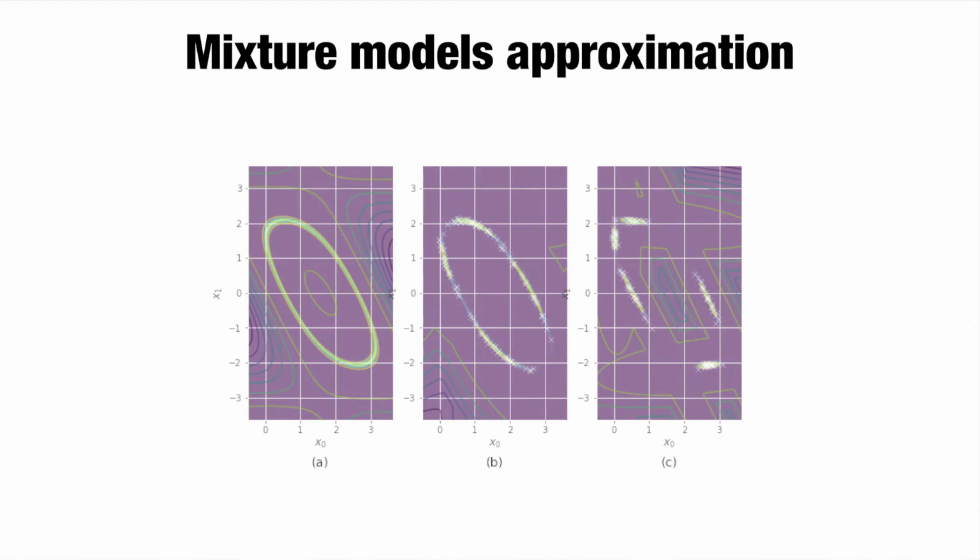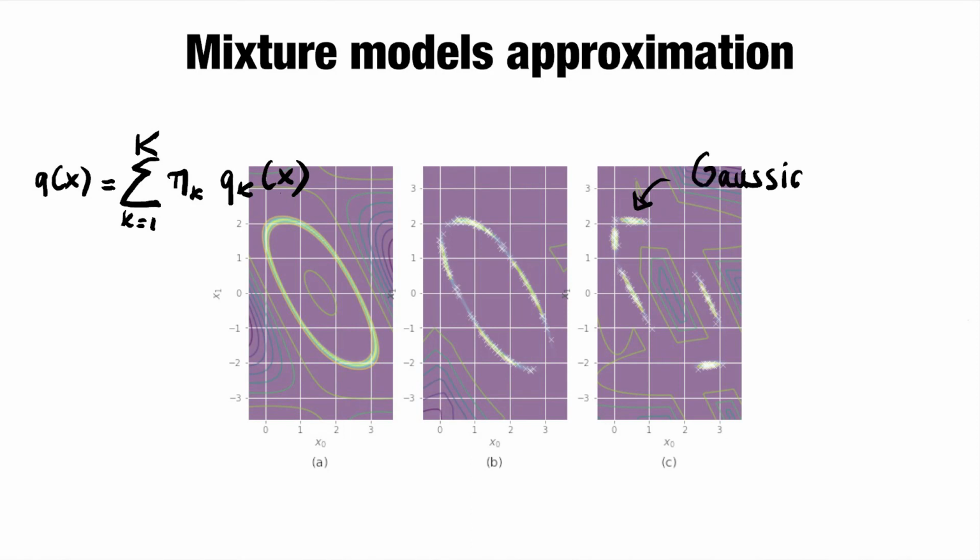We propose to use a mixture model as an expressive distribution to approximate our product of experts. A mixture is built by summing the probability of several simple models. As component distributions, we can choose Gaussians with a full covariance matrix or more complex distributions like bananas, which are Gaussians through a differentiable mapping. They are particularly convenient to represent inverse kinematic solutions, which are highly correlated.